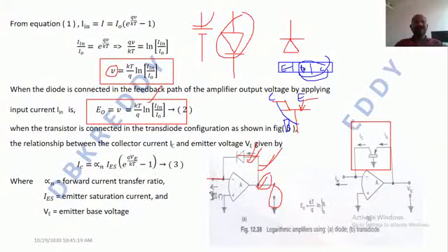It is a PNP transistor. Now whatever the transistor you are seeing over here, it is a PNP transistor. So when you are shorting the base and collector terminal, then the PNP transistor is converted into the PN junction diode.